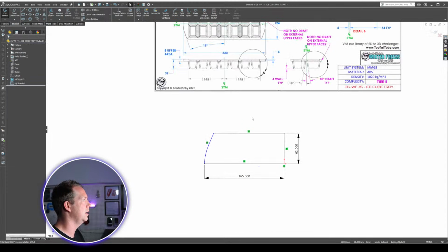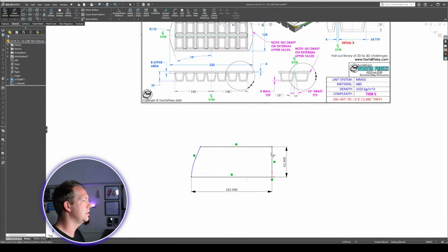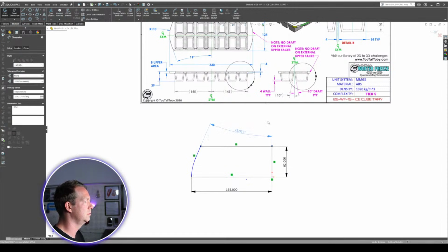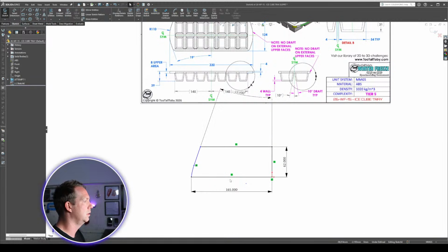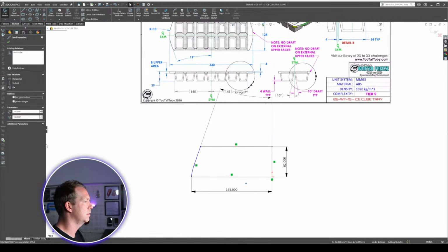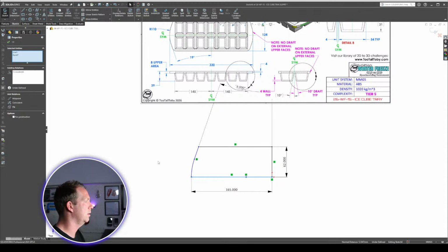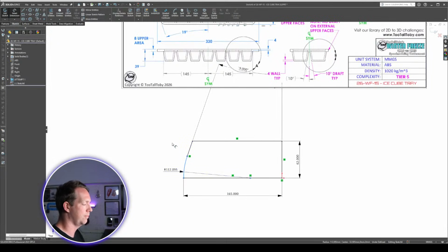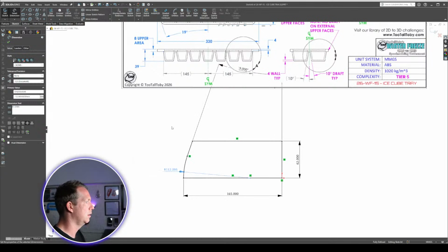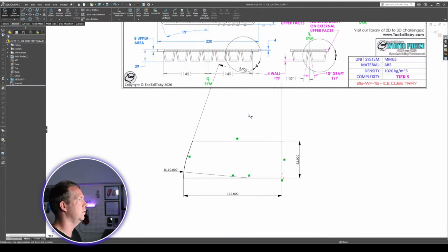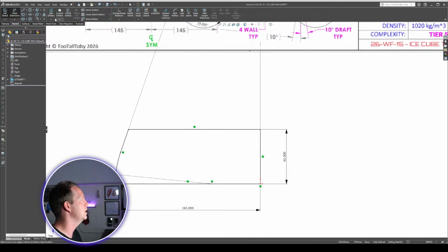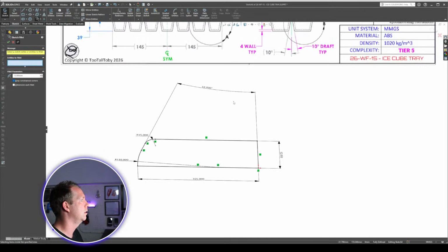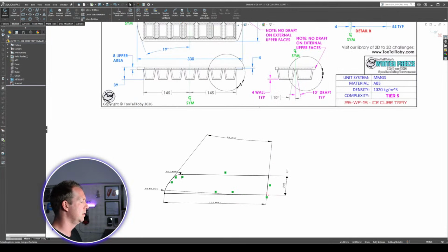So put that straight line in, and that straight line lets you then do the 19-degree angle. This center point needs to be coincident here. We can put in that radius, the 110. Okay, now that whole quadrant's fully defined, then we just get that radius of 15. All right, and then extrude.